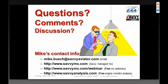Great. Okay, John says, thanks for your thoughts. After attempting to run lean of peak on my Barron's IO-470-L with GAMI injectors for years without success, will now gauge the lean of peak with CHT. Yeah, I'm curious why he didn't have success with it. The IO-470 should be an engine that should run lean of peak without problems if it has tuned injectors installed. But if he's having problems running lean of peak, he's welcome to drop me an email, I'll be happy to correspond with him about it.